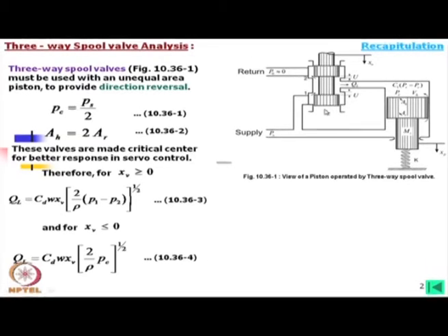But sometimes, instead of this continuous groove, we may have a rectangular hole. Then the length of this hole along the spool sleeve is equal to the height of the spool length for critical center. However, we sum up this groove width to get W. So, for example, there are 4 grooves which are perhaps spread over only 15 degrees or 30 degrees, then we simply add this W to get the orifice opening area.